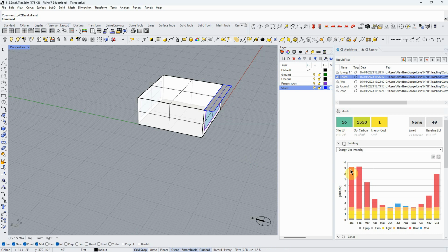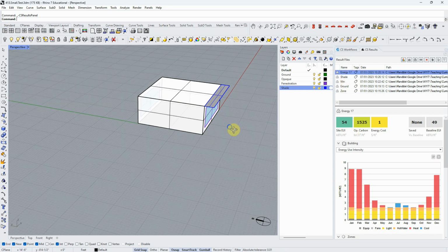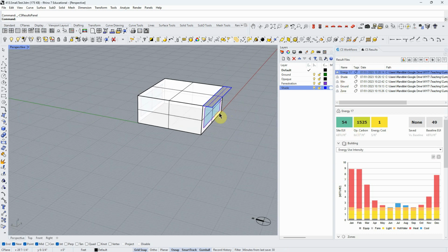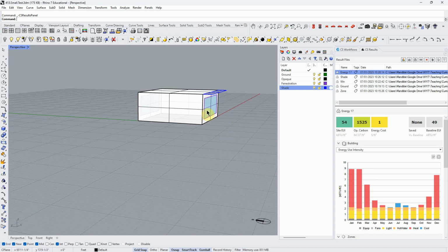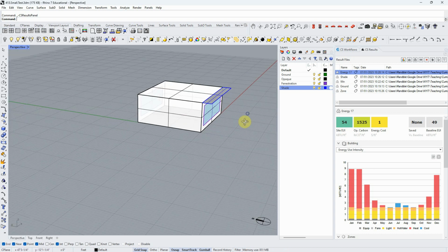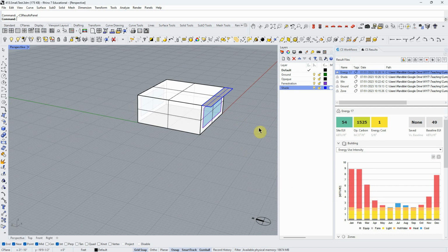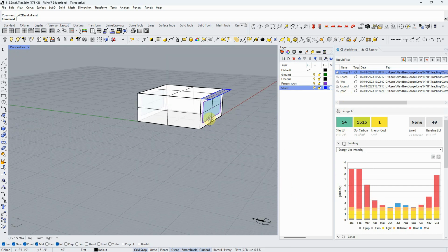Yeah, so see the heating load here goes down a little bit because I'm now letting sun in with that overhang into this glass. I'm losing a lot of heat through the glass, but I'm also gaining some. And so the balance is in the favor of having that overhang. But is it? Let's see. It's almost the same. So now we're kind of back to where we were with the window itself. We're a little bit better in our carbon here, and this is a big number. So like we're probably at 54.2 here and 54.5 here, or something like that.